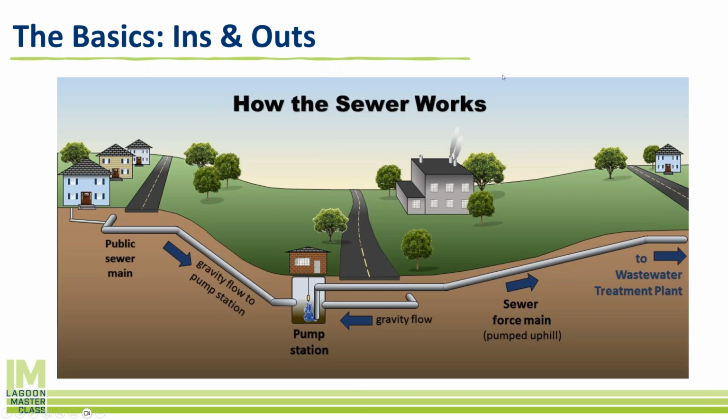How does the water hydraulically get there? Again, I know 99% of you already know this, but let's just cover the basics. We use primarily the same thing, gravity. You'll find that most lagoon systems are at the lowest point or one of the lower points in a town or municipality, oftentimes down by a river. Different wastewater discharges, whether it's municipal homes or industrial plants, will discharge their water and it will gravity flow down towards the lagoon system.